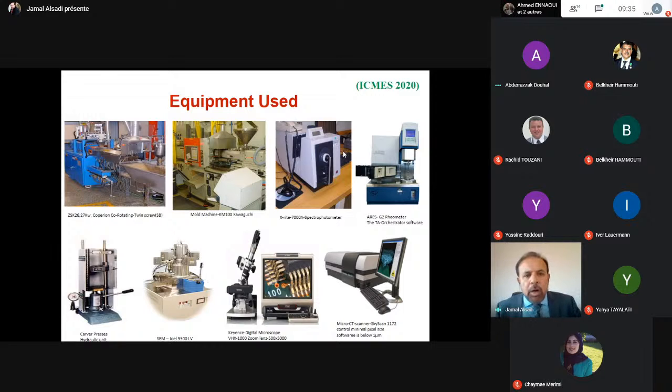If you are going to paint your car and they mix some color for you, you will get a different color. This is a complicated issue in order to characterize the right color. Mixing different codes gives millions of colors. Because of that, they manufacture the spectrophotometer to give very accurate readings, not dependent on metamerism or on your eyes.